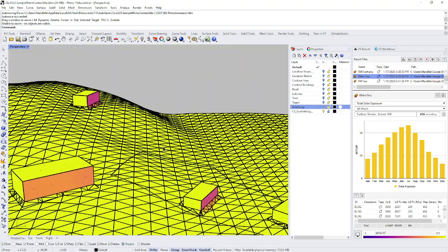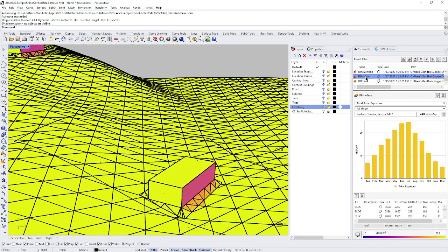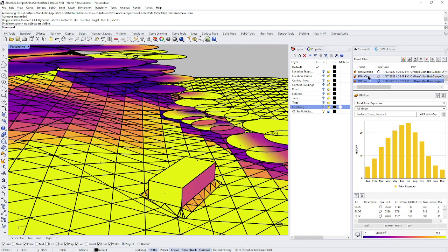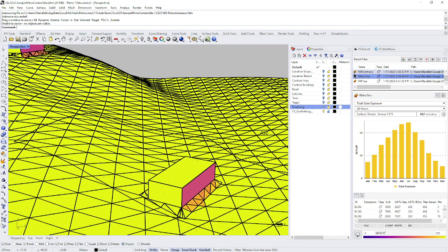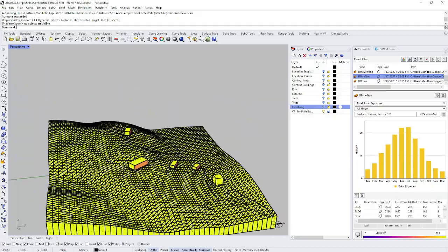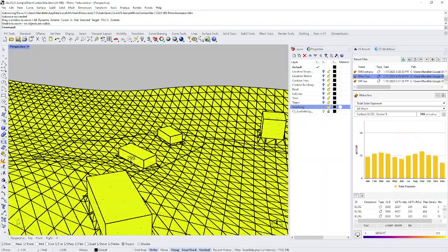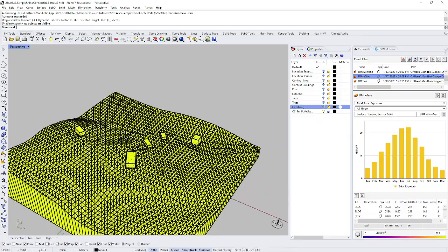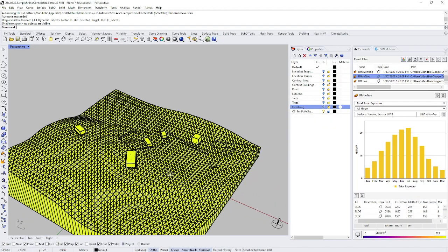And the north's going to be much less, right, for all of them because of the way the sun moves through the sky. So with the trees, it's 110. Without them, it's 116. The overhang's not going to affect it. So it seems like the southern side is the one that's being most affected, which makes sense in the northern hemisphere.